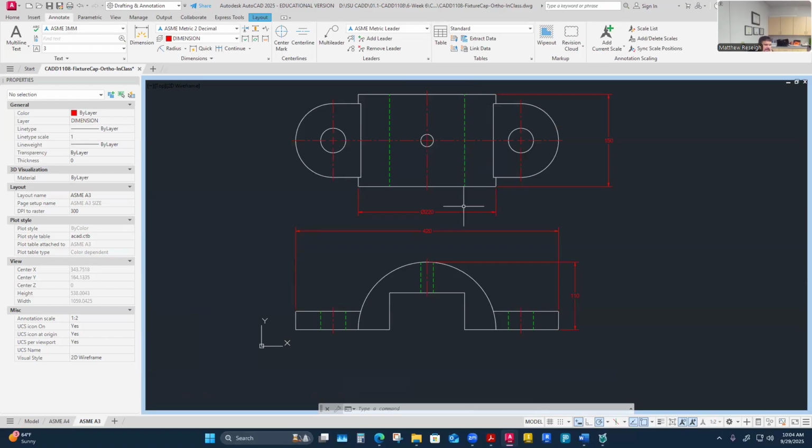size, right? Its size is 150 by 220, and its location, well, you'd be like, how do I locate that? Well, it would be like adding its location to a center line. So I feel like I could locate this part in space, lock it down in space, with a dimension from this center line to this edge, where I'm already using the front surface as potentially a datum, this surface here. And I'm definitely going to start using the bottom surface as a datum. And that's where 110 is being pulled up from the bottom.